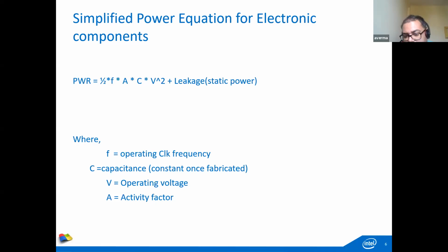Or you can have various other policies, which we call governors. If there is an app launch happening, you were at 2 gigahertz, you can directly go to 4 gigahertz because it's an app launch, right? So there could be different policies to give you a performance boost, and when the work is done, you can go back to a lower frequency to save more power.